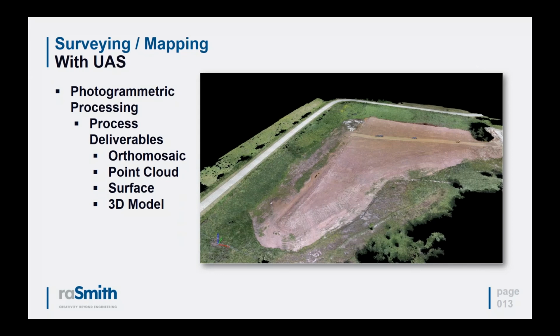We really like the volumetric type surveys using drones in that capacity, because it gives us the ability to capture a lot of that finite detail and give what we believe are even more accurate computations in terms of volumetrics, especially when you have bare earth or raw material exposed versus vegetation.